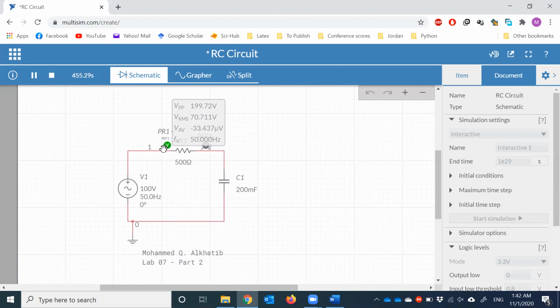So basically, if you are given this circuit and you want to solve it in the exam, so far we have been working only with peak values. Now, usually in AC analysis, we deal with RMS values. So the only difference is that you have to scale the value in the simulation by multiplying the RMS by the square root of 2. And that's it. That's the only setup you need to do for measuring AC voltages and currents also.